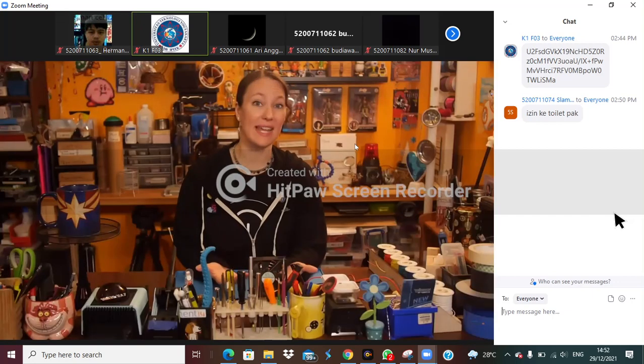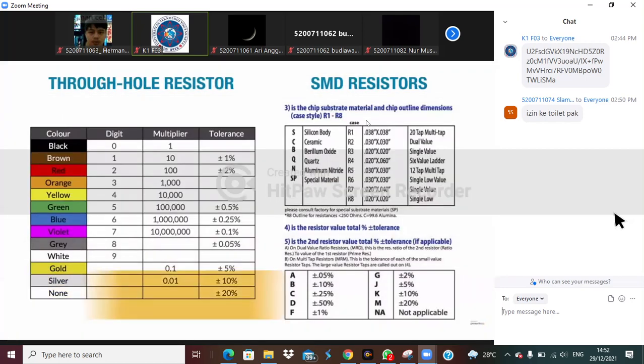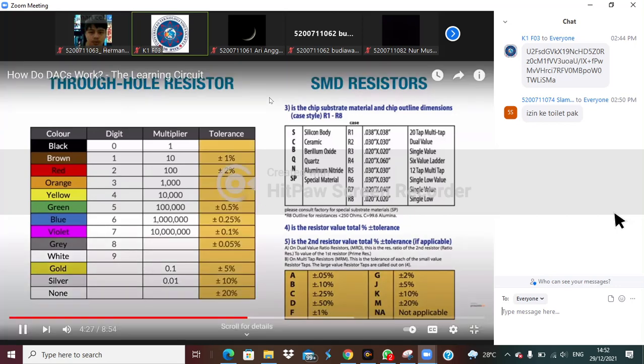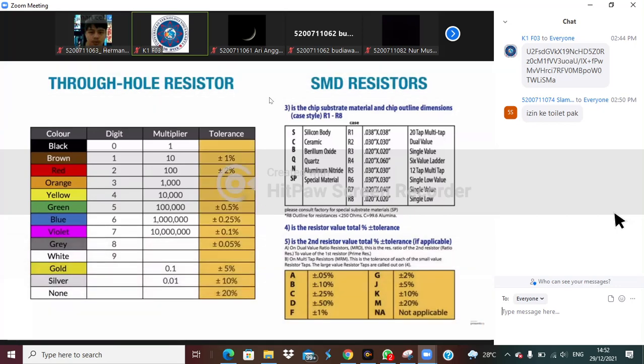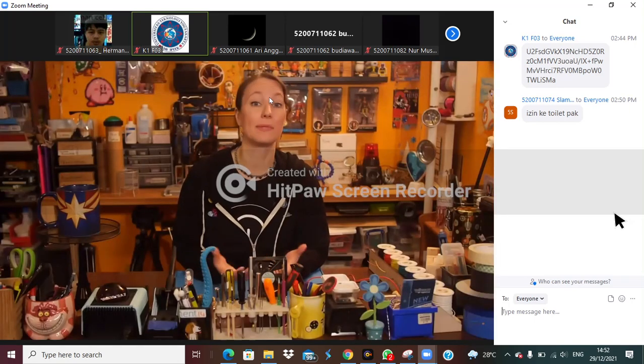With this DAC, as the resolution increases, a larger variety of resistor values are needed. Due to the manufacturer's tolerance of the resistors, the higher the values and the wider the range of values, the less precise they are, and the less accurate the signal conversion is. The next type of DAC has a resistor structure that helps improve upon those issues.